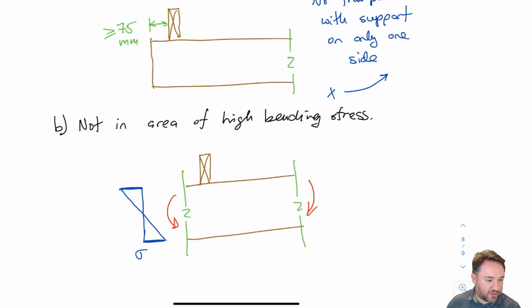There's two things that can happen. The first thing is, if it's tension in the top and the tension is really high, then that means that the fibers at the top surface already have high axial stress in those fibers. They already have high tension. So then we can't rely on those fibers to take additional tension caused by the trampoline effect. For the side that's in high compression, basically that means if the fibers are all bunched up and they're in high compression, then I may not be able to actually engage the fibers in tension at all. They may be in compression that entire time. So again, if I'm not engaging the fibers in tension, I can't have that trampoline effect. So both sides don't work.